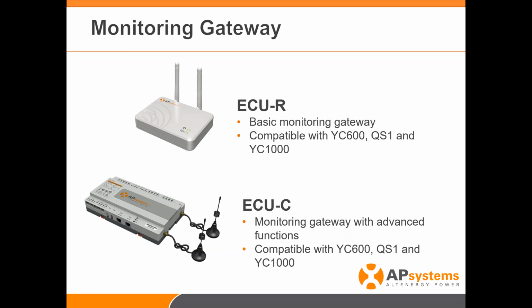So Chris, I have a question that was put in the chat, which I think you addressed: do the inverters communicate with the ECU even though there's no AC grid connection during the install? Yeah, great question. That's the power of this system. We're able to go through the process, turn the ECU on, and the inverters themselves will turn on with that first solar panel plugged in. They'll start to communicate.